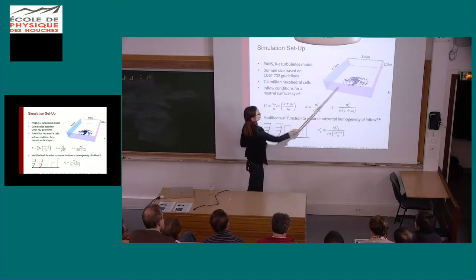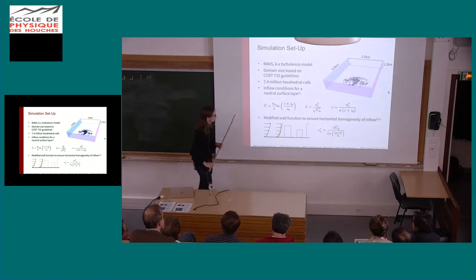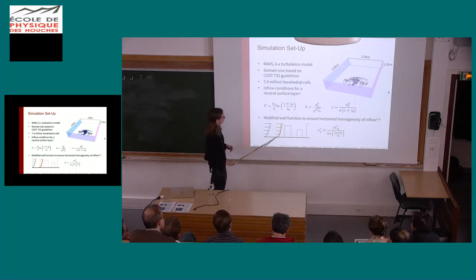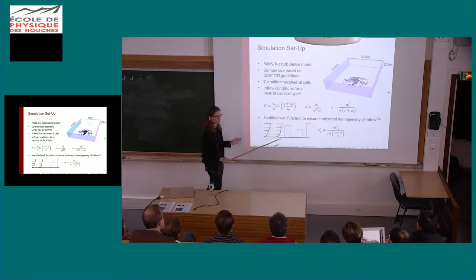Because the boundary condition needs to be far enough from the first building, that profile actually starts to develop and you get something like this. So if you're interested in what happens at this level, at pedestrian wind comfort, for example, and you already have like a 30% increase in velocity here, that is purely because of numerics and modeling,